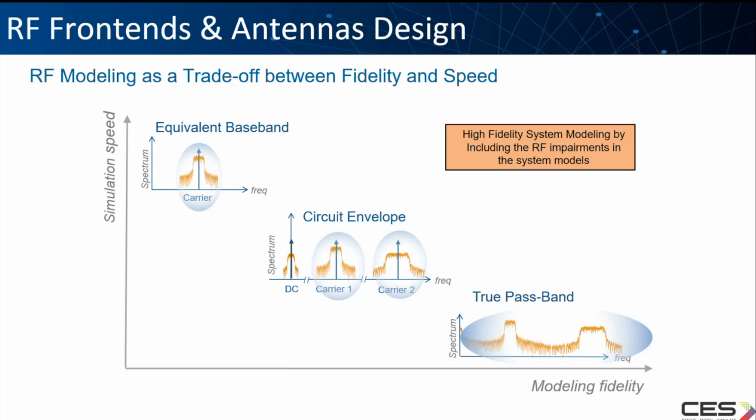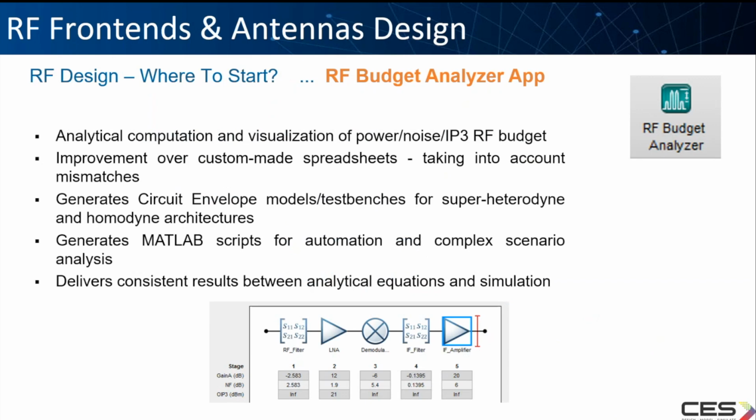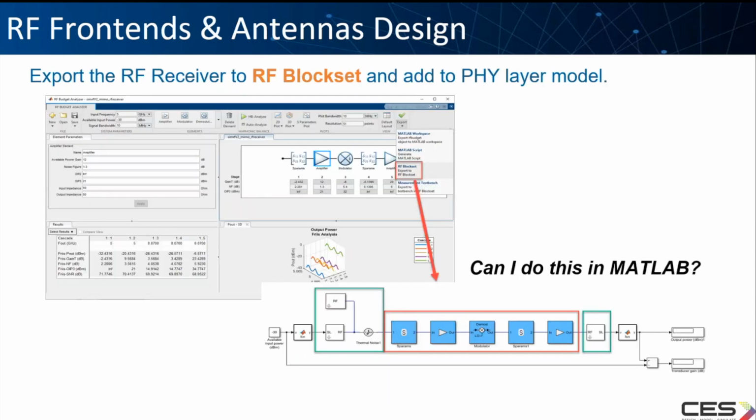They allow you to perform the design and this analysis by looking at the nonlinearities and the power. That can be done interactively using an app called RF Budget Analyzer, which helps with performing the frequency analysis, the harmonic balance analysis, and also with visualizing the S-parameters, the losses, and so on and so forth. It also has exporting features to MATLAB and Simulink. The app is fully interactive, and it also helps with understanding the RF front-end design.